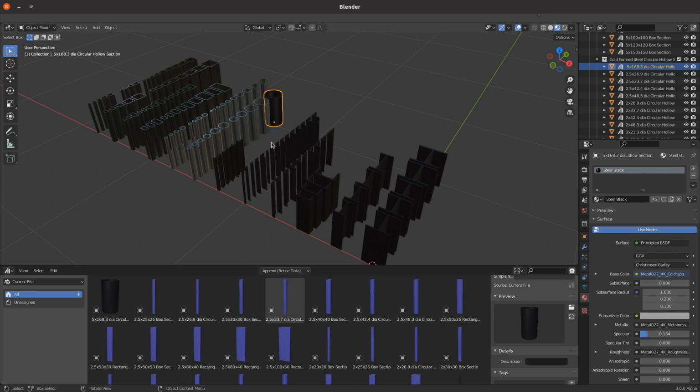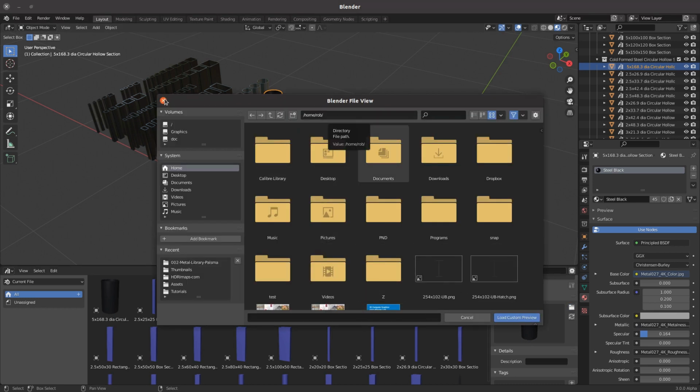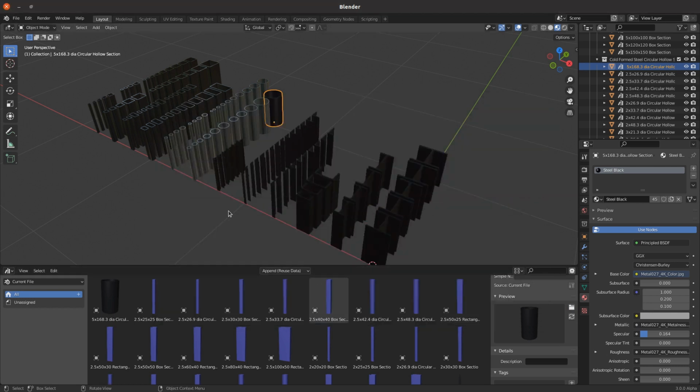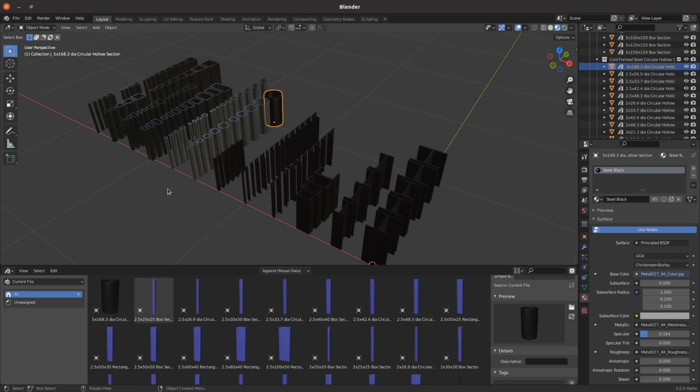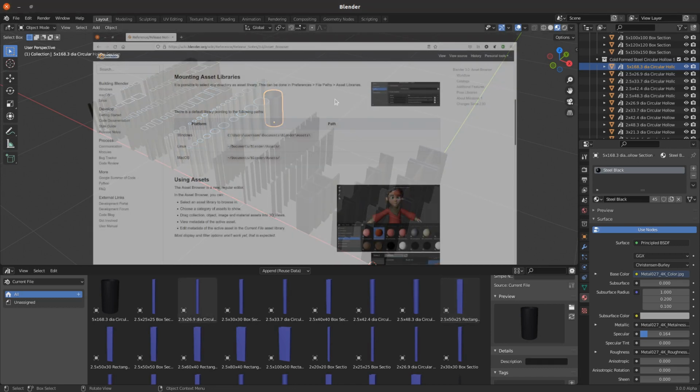You can also take your own screenshots or renders of each of the components and bring them in through the file browser. I'm not going to do that, but it's something that you can do when Blender 3 becomes more stable. If you're building a complex asset library, you can have much better thumbnails than the standard that gets imported in. The last thing to do is to save the asset browser, and the Blender website gives you locations of where the default browser would normally be located.